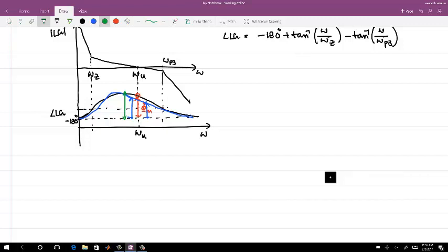So if on the phase curve your unity gain frequency is placed such a way that your phase margin is on the downhill slope, or let's say uphill slope, then with a slight variation in the component parameters, you will see a change in the phase margin. Whereas if you are at the peak, if your component parameters change slightly, in the same variation, if the slope is 0 at that point, then the phase margin deviation will be lesser with the change in the component parameters or any loop gain parameters.